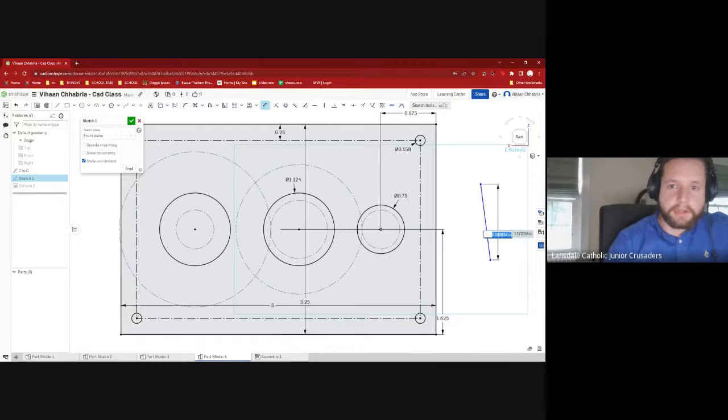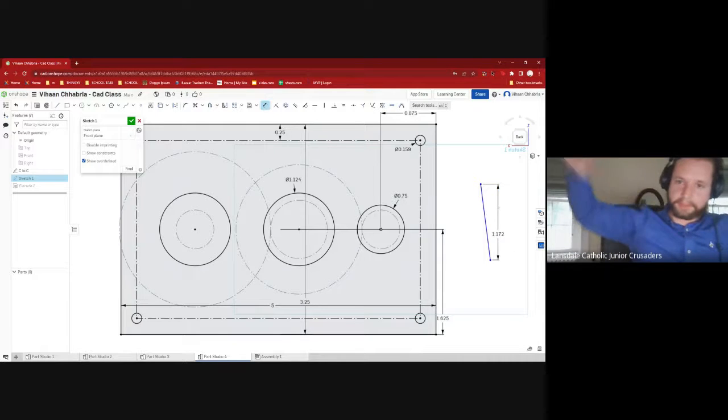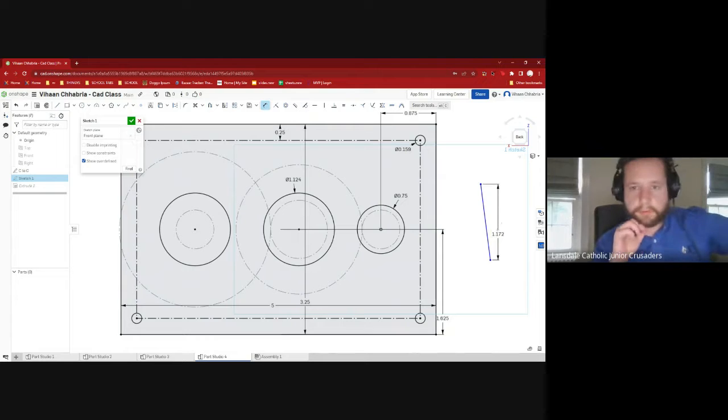Make sure it's not. Oh, nope. Do you see how that fixed it so that it was measuring perfectly horizontal? Oh, yeah. I want you to make this dimension so that it goes parallel with the line and it doesn't just go vertical. Okay. And that'll be important. It's not really important right here, but it will be important in other things you do. So I'm just going to show you and everybody else here. So just click the dimension, delete it, and then click dimension again. Point to point.